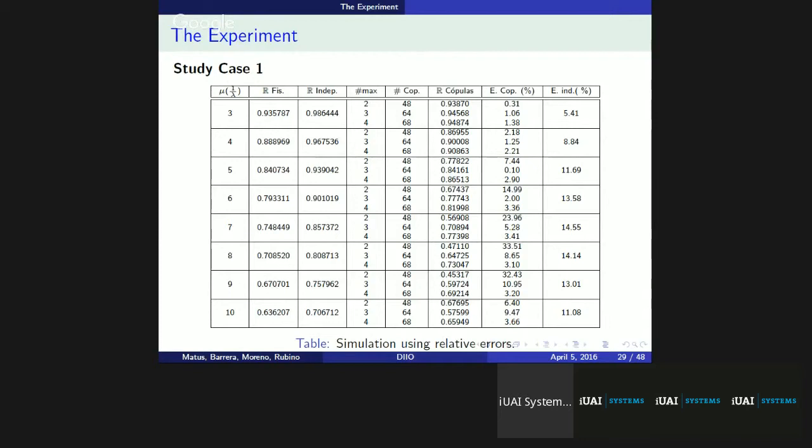That is copulas of 1 and 2 components. And with that, we have 48 copulas, and we obtain a reliability of 0.77. That is not really good. But if we take 3 components per copula, we can obtain a reliability of 0.84. That is very close to the real value. It is the same within the confidence interval.